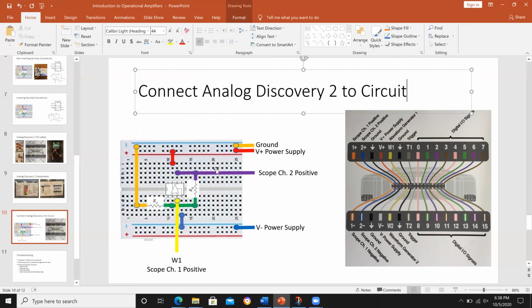So with those 2 resistor values and the non-inverting configuration, that gives me a gain of 3.12. Now that's what I expect if both resistors perfectly match, right? Like if RB is perfectly a 10K and if RA is perfectly a 4.7K. In the real world, again, remember that gold band, the 4th one, the plus or minus 5%? That's the tolerance. That's where you're going to have variability. And that number, your gain number, will be slightly different.